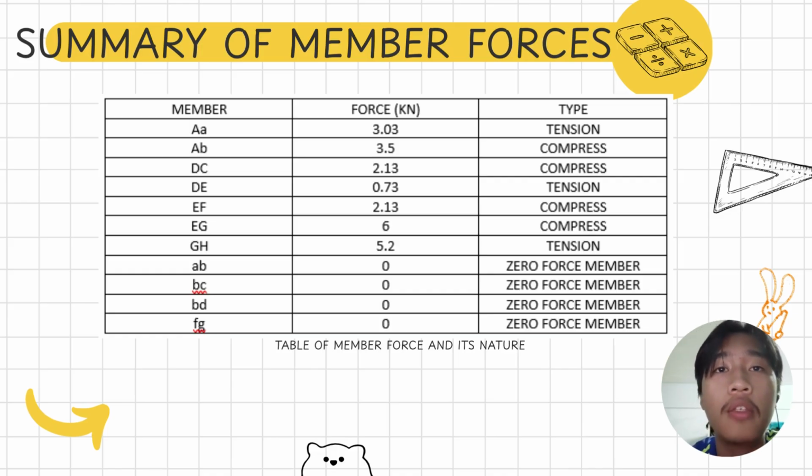Next, for members under compression, member AB experiences 3.5 kN, DC and EF each carry 2.13 kN, and EG carries the highest compressive force of 6 kN. This suggests that EG is a critical member resisting compressive loads and is more prone to buckling if not properly